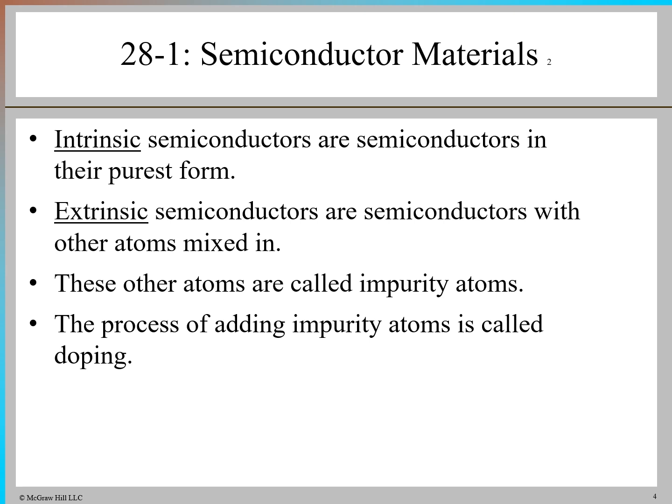Intrinsic semiconductors are pure semiconductors, such as a silicon crystal made only of silicon atoms. Extrinsic semiconductors are created by adding impurity atoms through a process called doping. These impurity atoms, which have fewer or more than 4 valence electrons, alter the semiconductor's conductivity. At room temperature, intrinsic semiconductors behave more like insulators, while extrinsic semiconductors have greater conductivity depending on the amount of impurity atoms added during doping.